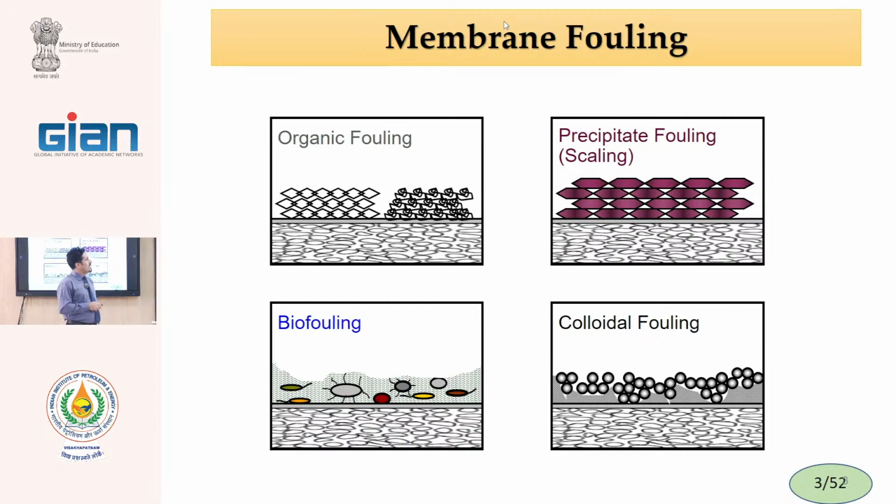And these crystals can act as a knife and can destroy the membrane surface, can cut the membrane surface. Therefore, this type of fouling is very dangerous. The colloidal fouling can be removed easily, but the scaling is hard.